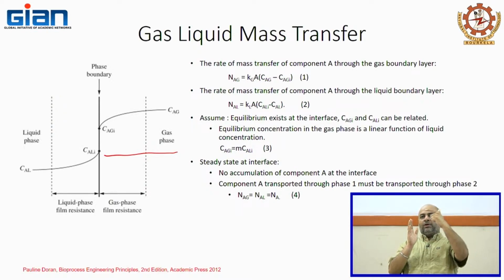So, when your concentration comes in, it is at a lower concentration at the surface than the concentration that was there in the bulk. Then from there, when it goes into another phase, there is a drop. Let us say if I use a membrane, there will be a drop in the concentration within the membrane if the concentration on the left hand side is pretty high compared to the right hand side. That would be determined by the diffusivity or permeability of that membrane, how much of the material can be diffused through at a given time.